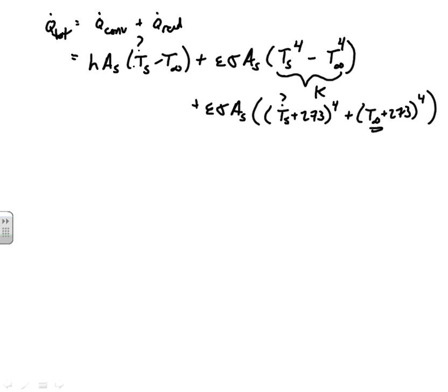We have everything, but in convection we don't know what the heat transfer coefficient, h, is. But we know that anytime we're getting one of these heat transfer coefficients, we have to rely on experimental data. Now, just talking about the natural convection component only, we have to calculate the Rayleigh number, okay?